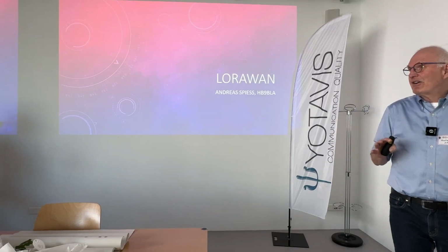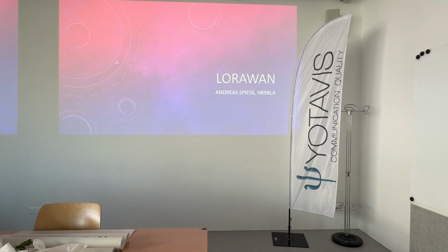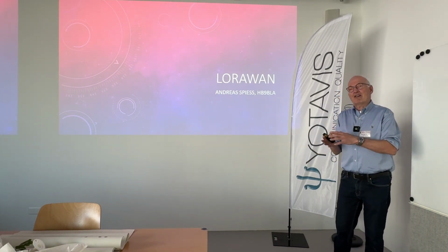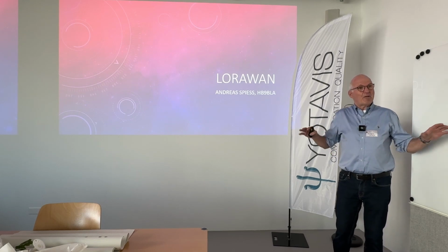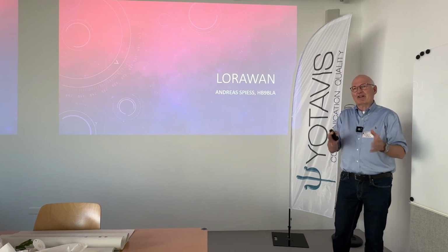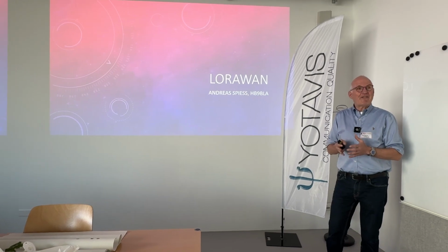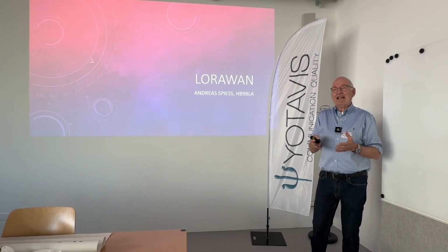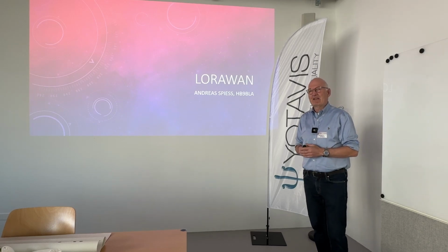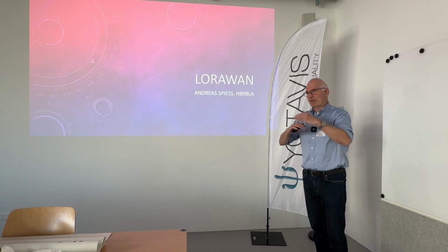We heard now about the LoRa modulation. And people sometimes mix LoRa and LoRaWAN. LoRa is the modulation, as we saw, like SSB, like CW, like FM, whatever. LoRa is just a physical modulation. And LoRaWAN, as it says, wide area network, is a network which uses this modulation. So this is one level higher in the networking protocol, at least.